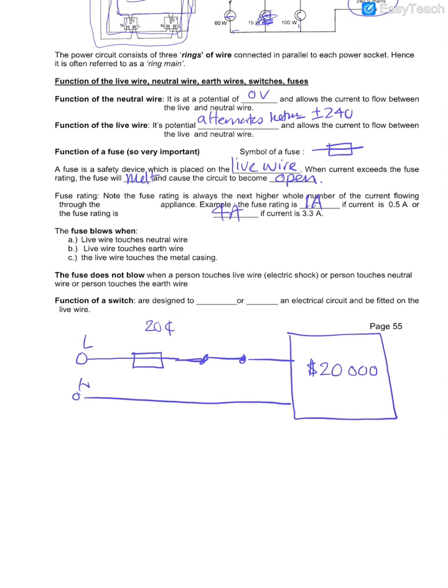Then after that, the computer is 240 volts, let's just say it's 2 amperes. Then you put in a 1 ampere fuse, and you close the switch, what will happen? The fuse blows, right? The fuse can only take 1 ampere, so straight away this is going to draw 2, you will blow the fuse, melt. So every time you start, the fuse blows, cannot play. Very frustrating, because he forgot the physics lesson already. So he got frustrated and fed up, and uses a 10 ampere fuse.